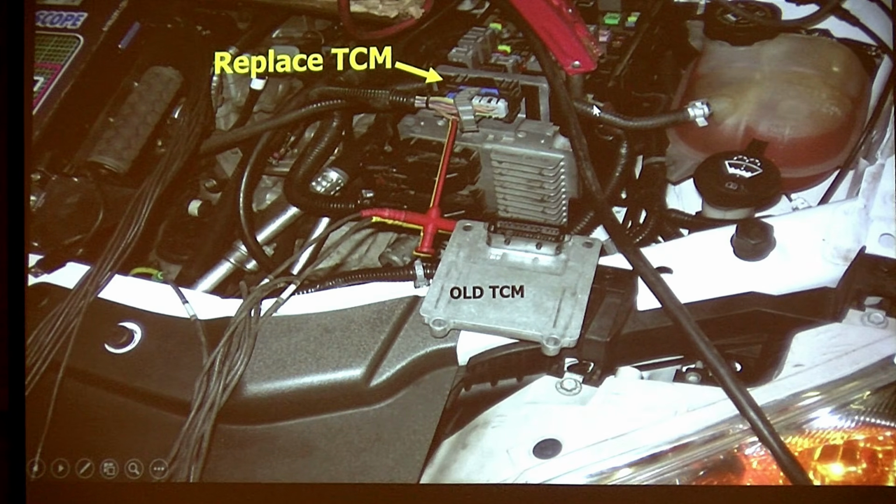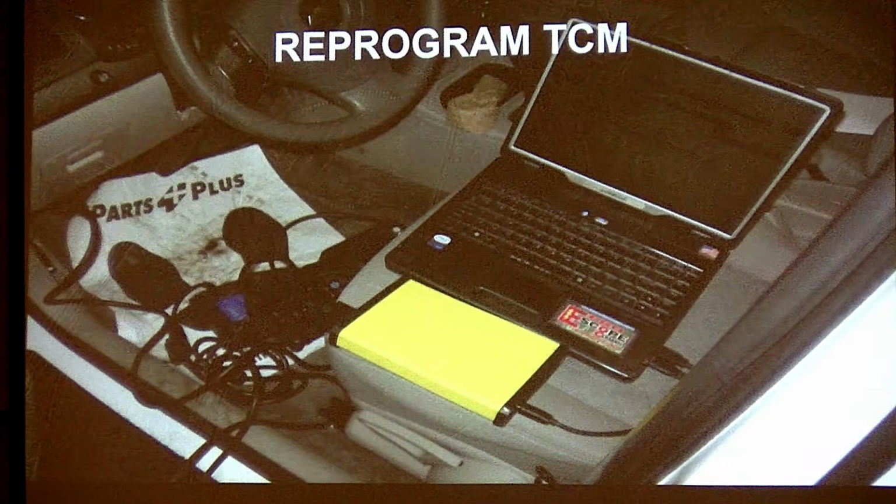The transmission shop did this. They blew the module when they pulled that up. They were pulling the transmission and they lifted that module up and it hit that power post on the battery. It's done popped right there. I see this happen quite a bit. This is another one I see a few times.